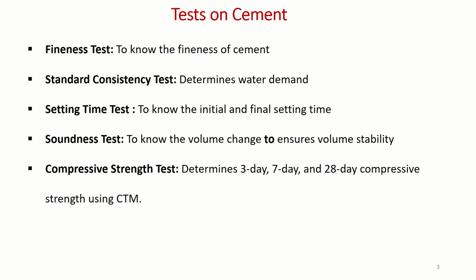Tests on cement are conducted in the laboratory as well as in the field. You know very well the field tests. Whenever any fresh sample comes on the site, there are a few field tests: cement should be greenish gray, should be very fine, and should not have any sort of lumps in the bag.